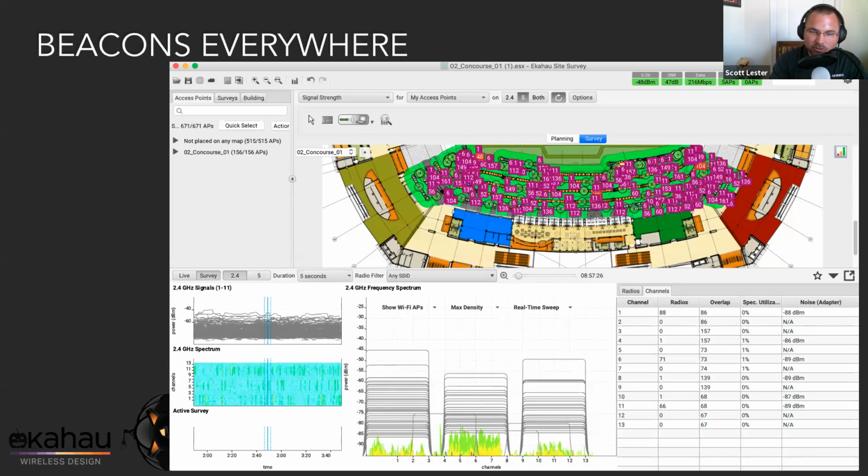Yeah, and if you look at the screen, you'll notice that I changed the slide, and this is actually looking at 2.4 gig now. I think it's worth mentioning briefly that 2.4 is definitely something you want to deploy in a stadium. Because again, airtime being our most precious resource, we want to utilize as much of it as possible, even if we know that 2.4 gig is already going to be highly impaired. Even if we were able to squeeze out an extra 50K or 100K of usage, maybe for a handful of clients, something is always better than nothing in this case.